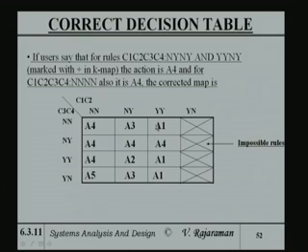The other A1 is sitting here. This A1 has a don't care neighbor which can be combined with that. So, I can now take this 4, this 2 and this 2 and combine, because we can use the same action in more than one combination, one circle, or one what they call a cube in Karnaugh map parlance.